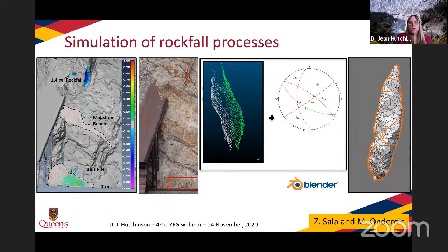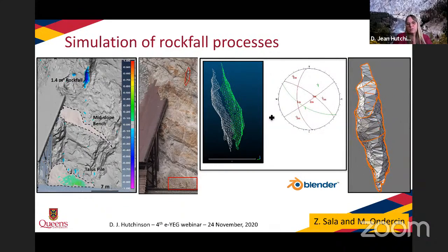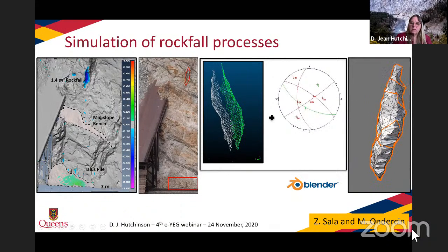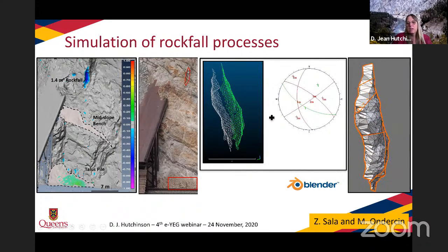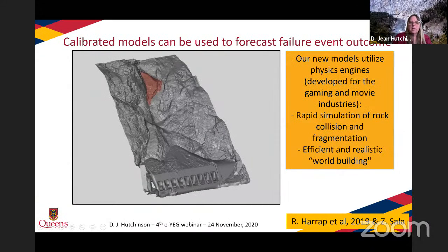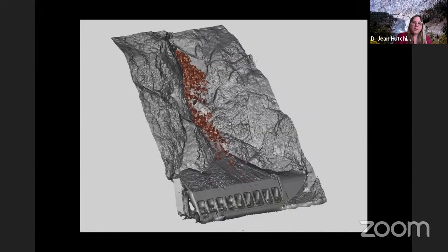of the slope. When we take this information from our change detection and also look at the structural geology, we can define a rockfall object such as you see on the right side, which has pre-existing structure along which fragmentation may occur. And when we run these types of simulations, you can see here, we see that the rock falls can fragment along structure or along boundaries that are defined. We can simulate the results of these types of events.